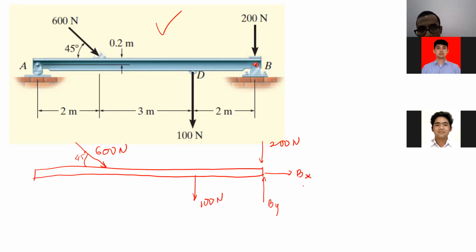Yes. Okay, a roller joint can restrict the movement in the vertical direction, but it will not restrict the movement in the horizontal direction because it's a roller, right? When we talk about a roller, when you push horizontally, it will move. Correct, right, Alberto? Yes. Okay, in that case, should you add the horizontal reaction force as well or not? All right, so just AY, no AX. Just AY, because it only restricts vertical movement.